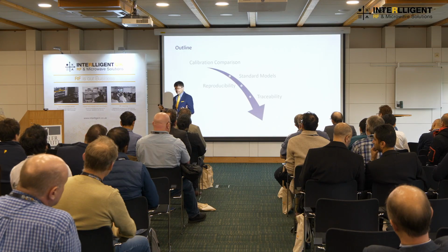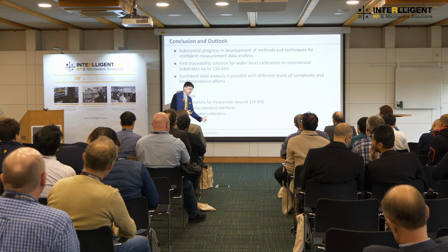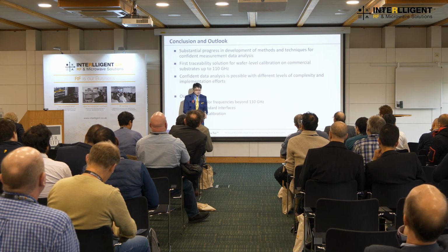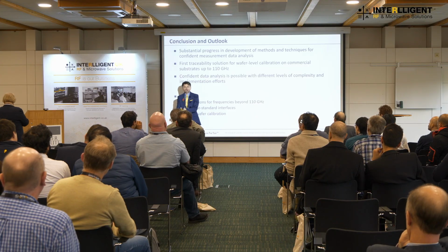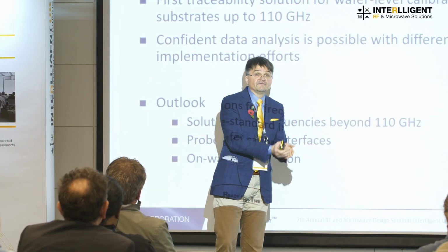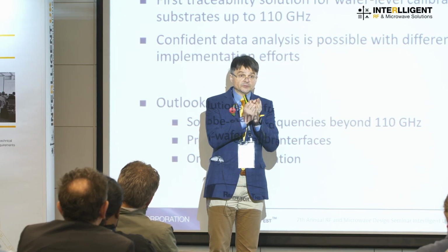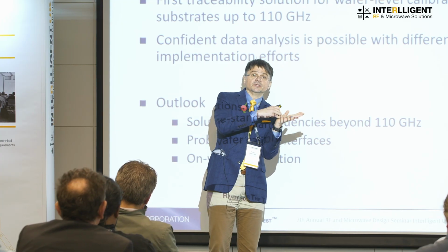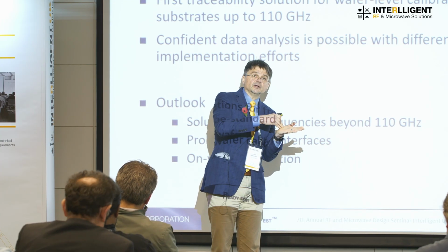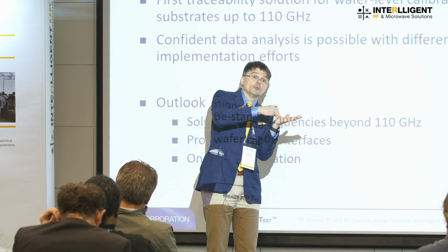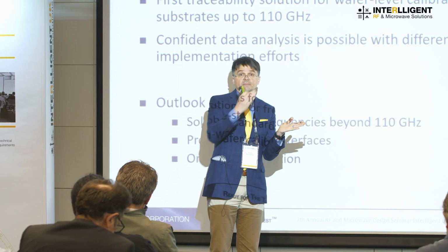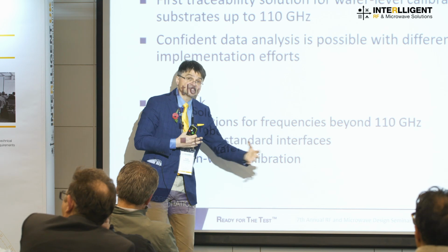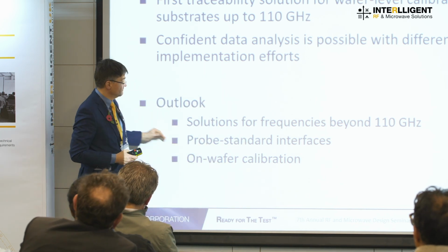Kind of a breakthrough, but I would say it's just the first step, because I need to be careful what I'm saying here. Is it a traceability chain like we know it, for instance, for power measurements or measurement of waveguide sections? No, because what remains unbreakable is the relationship between the standard and the probe. We can establish a traceability chain, but only in the given environment and for the given configuration of RF probe and standard. If you change the probe, the experiment must be repeated. Unfortunately, there is no way to split these two, the probe from the standard, today. But that's already a very big progress forward.